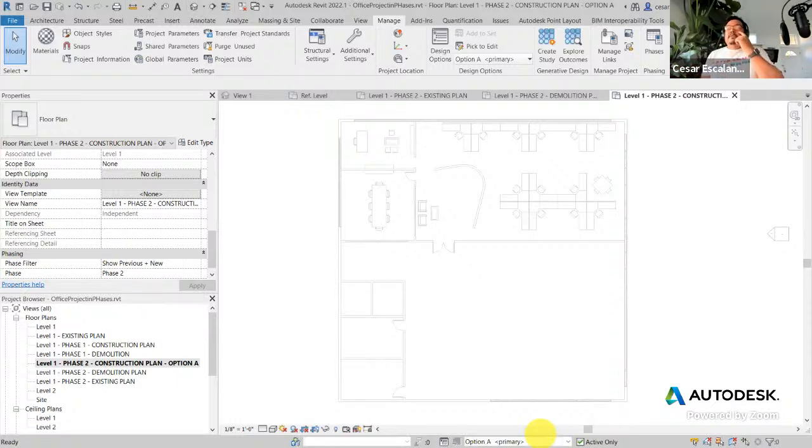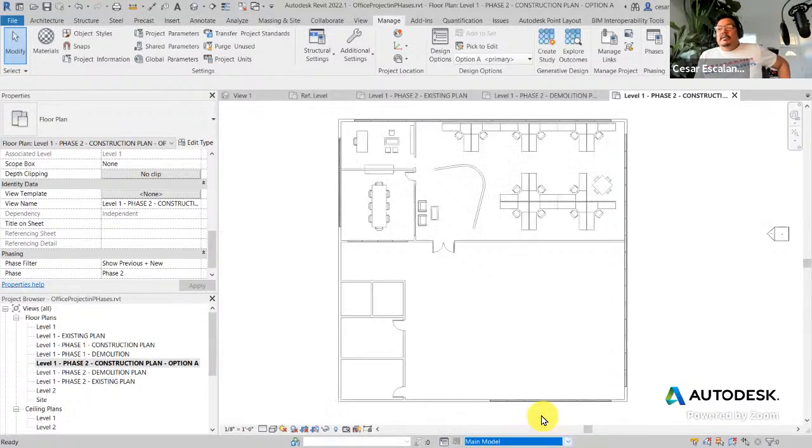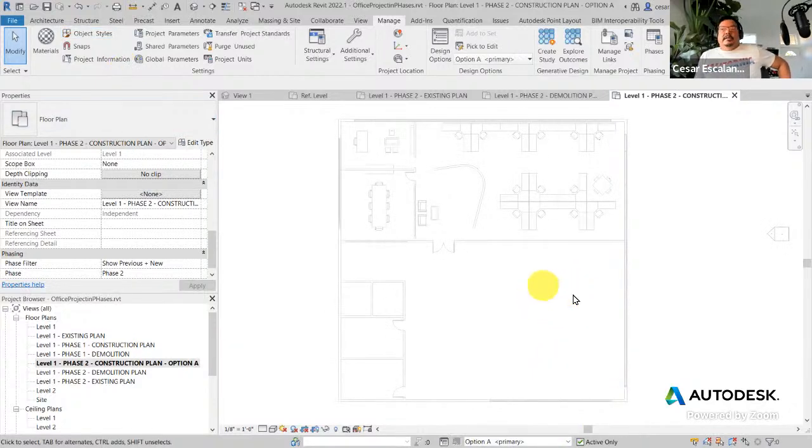You can move objects back and forth via copy paste. For example, if you decide, oh, you know, this thing, I placed it by mistake on the main model, it needs to be part of the option. Copy to the clipboard, Control C, switch options, and then paste it. And now right here, this is the moment where I start building a design option A. And you create your suite, and I don't have time for everybody to build a custom office suite, but I have, just like I did on the suite here, I have a solution baked for us.